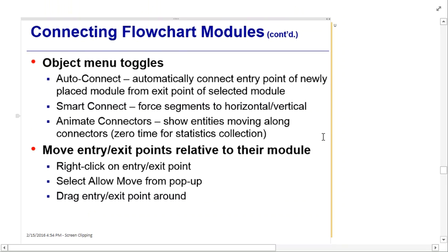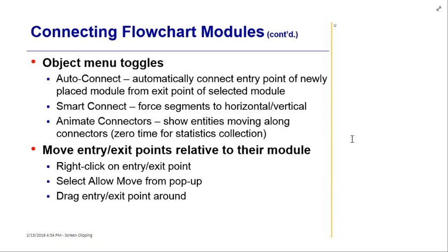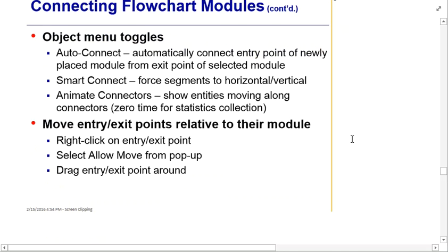And that's a great example where you would probably also use an Assign module, where you would change the entity picture, as well as maybe assign or change an attribute about that specific entity, which would facilitate collection of data, as well as by changing the picture, you get a good graphic of what's happening. So that's a very useful thing to do.